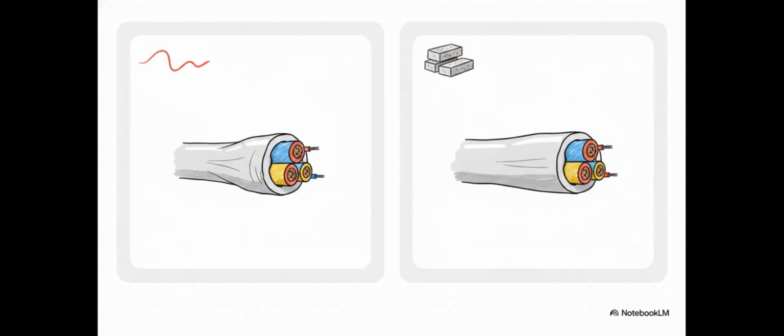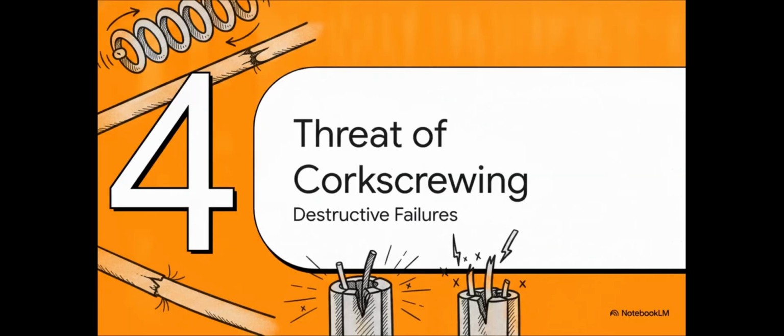And all of this internal architecture builds up to the outer jacket. For high flex, the jacket is often tube extruded, so it's blown onto the cable pretty loosely, or made of elastic silicone for maximum softness. Continuous flex is pressure extruded. The jacket material is violently forced under high pressure right into every single gap between those internal conductors. This forms a solid, rigid profile that absolutely locks the internal components in place so they cannot shift around during movement.